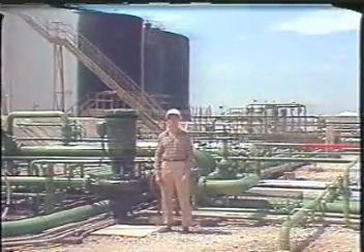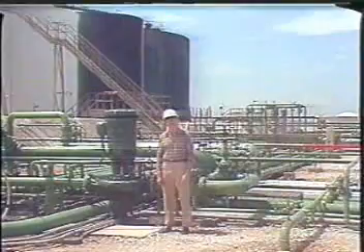In any case, no matter what type of priming is used, remember, priming the pump before starting is absolutely essential. An unprimed pump will, at best, be inefficient and most likely won't move any liquid at all. And running a pump without liquid will damage the pump. Now, let's take a look at pump operation, startup, and shutdown.